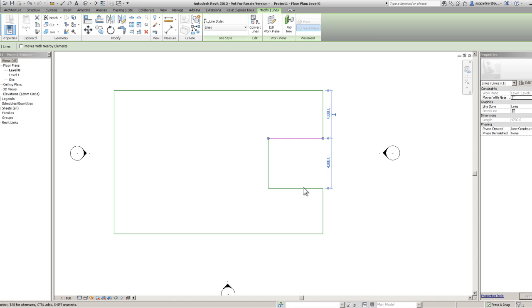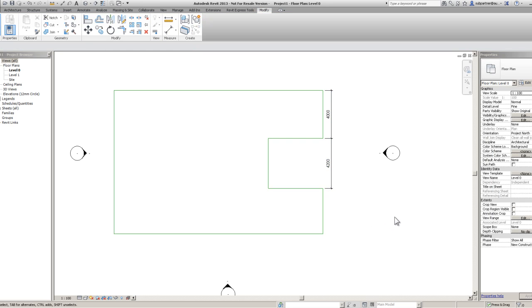Okay. Once we've done that, we're going to look at this. We have this little tool just here. If you hover over it, it tells you what it does, but it says make this temporary dimension permanent. Let's click it, show you how it works. I'm just going to click off of it, so that obviously I'm dropping anything I'm selecting. As you can see, the dimension is still there. It is now a permanent dimension. It's a proper dimension, as if we were drawing dimensions on our screen. If I hover over it, you can see how they're joined together. It's a running dimension. They are joined together.